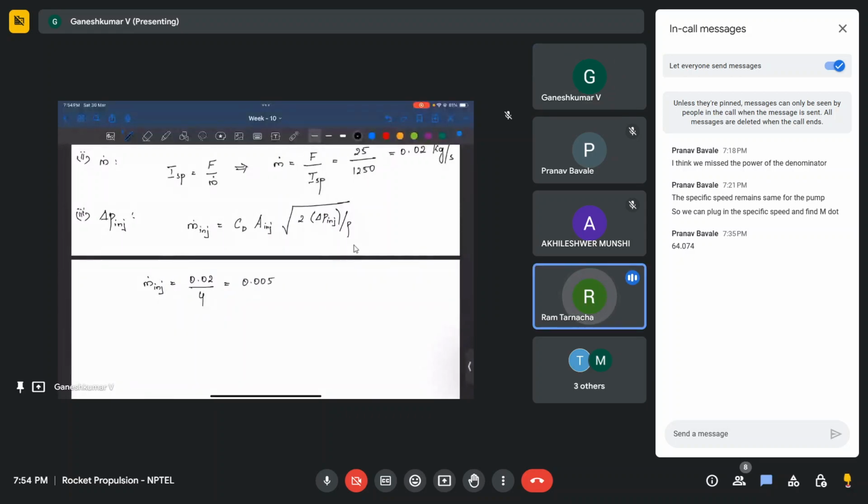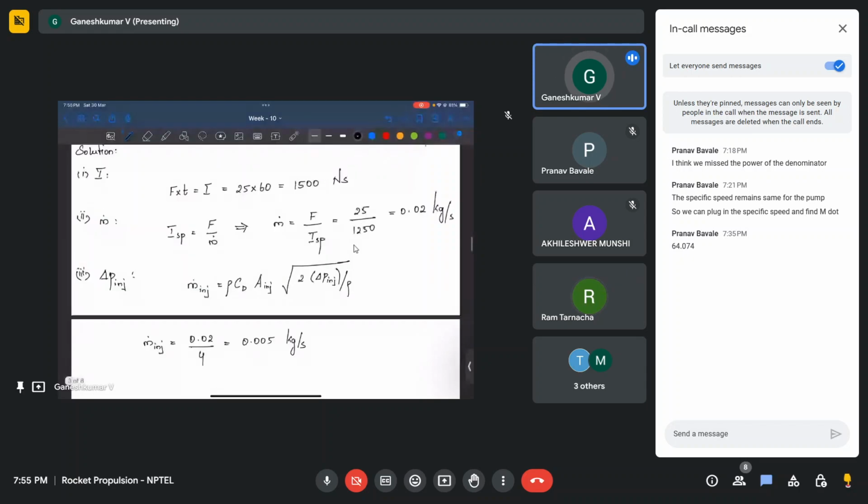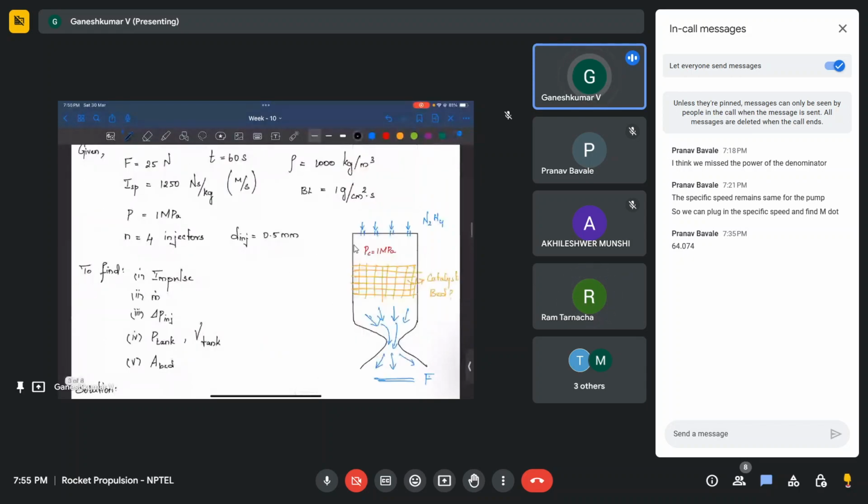Now, in this formula, you have to multiply it with the density also. Yes, sir. This is area into velocity multiplied by density to get the mass flow. Wonderful. So eventually it will come within the square root, multiplying with the delta P term. But we don't know CD, right? CD is not given in the question. So for this, maybe I will take CD to be 0.96.